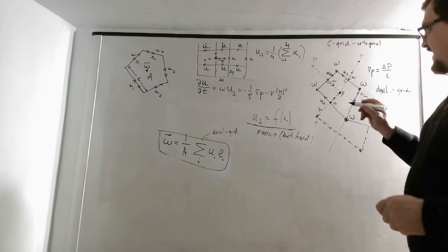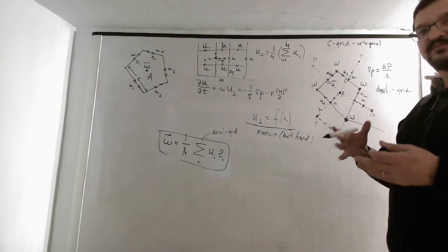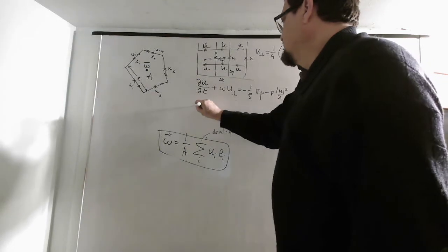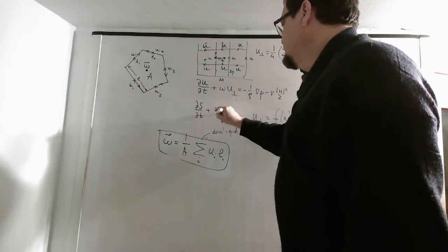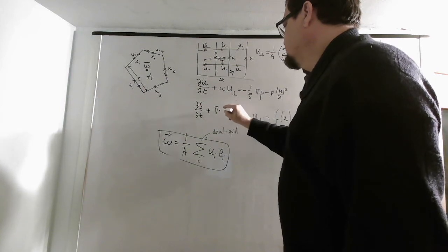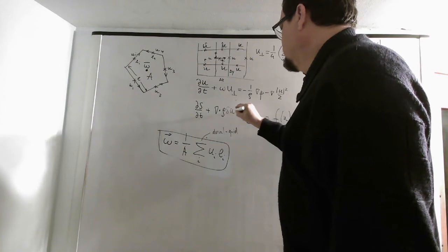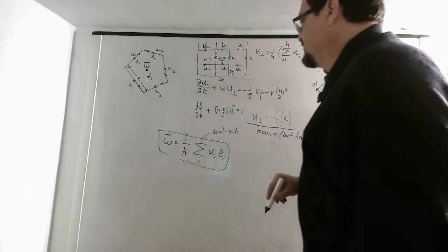Now the same way you can actually compute divergence. You need divergence to compute evolution of scalars, right? Because for a scalar quantity, ds/dt plus divergence of the flux of rho s u equals, say, 0.